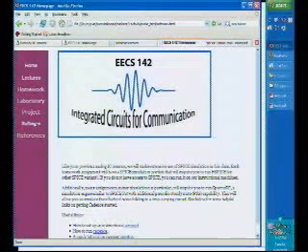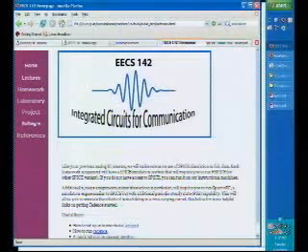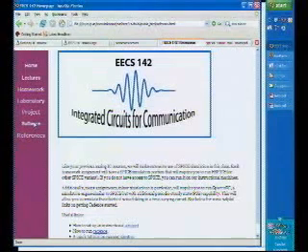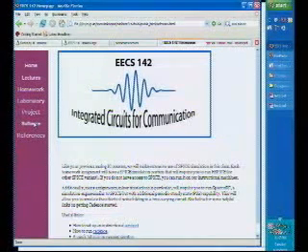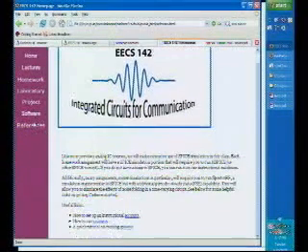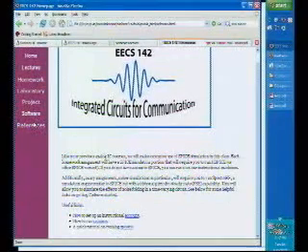For the first half of the course, you could probably just use HSpice, which is something most people are familiar with. Second half of the course, you're going to need to run SpectraRF, Cadence's SpectraRF tool, which is able to analyze mixer noise. SPICE can't do that, and we'll learn why later in this course. So at some point, you might want to make the transition a little bit early to Cadence. Cadence also has a graphical environment where you can draw schematics and do all those neat things. But if you like the text interface, that's fine. Whatever is easy for you guys. So try to get the software-related issues resolved early in the course.